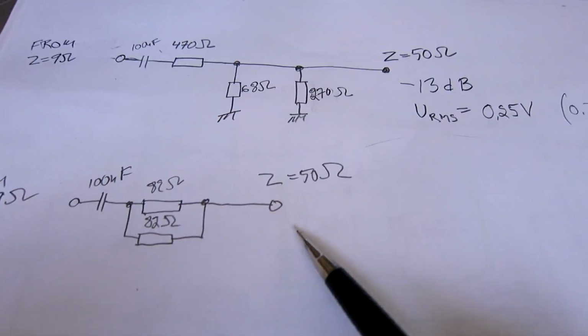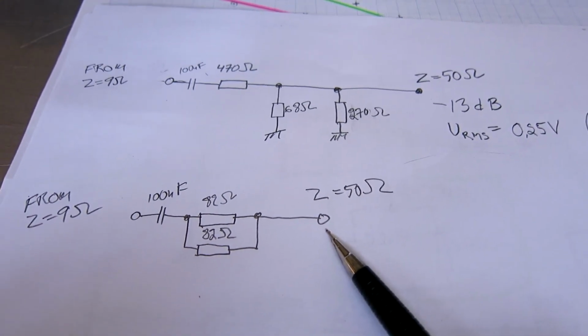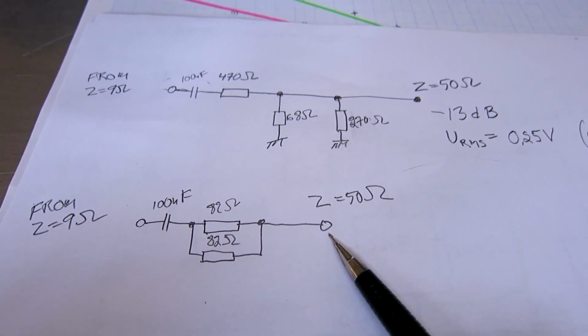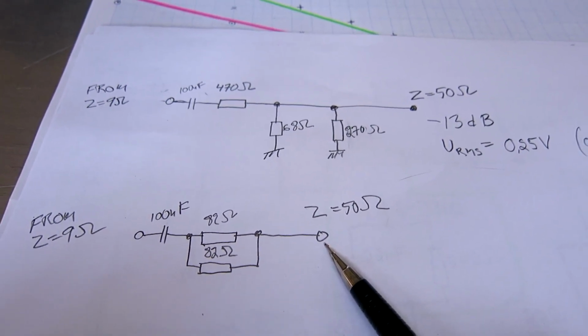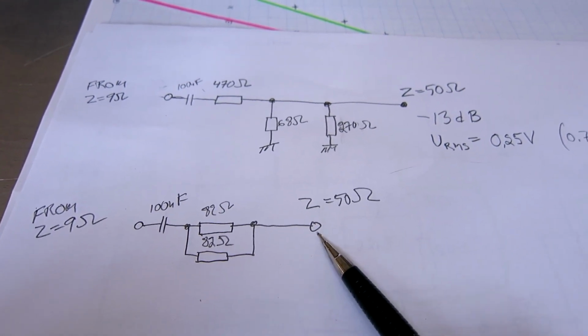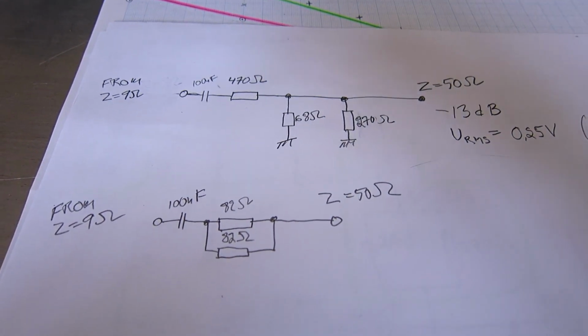This also gives an impedance of 50 ohms here, but much more signal, of course. There is no risk for saturation in the transistors at 60 decibels lower level. So I wanted to maximize the signal going into the 2-channel receiver.